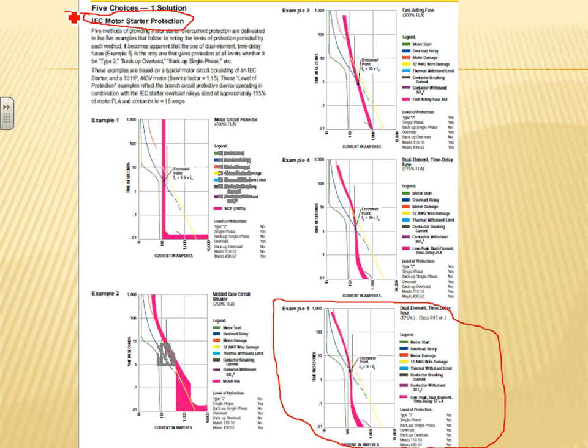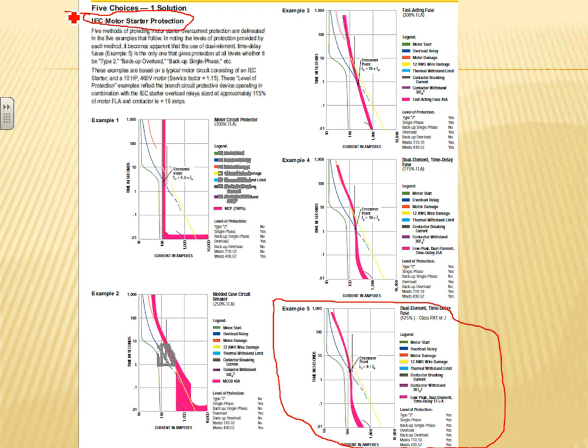I don't know if you guys use a lot of IEC or NEMA; most of the stuff that we use is NEMA. But when you go to a manufacturing plant, especially now, a lot of manufacturing brings a lot of IEC stuff from Europe, contactors and so forth. So you might encounter a type 2 protection that requires you to limit the let-through energy, and the only way you can do it is current limiting fuses. Any comments, guys?